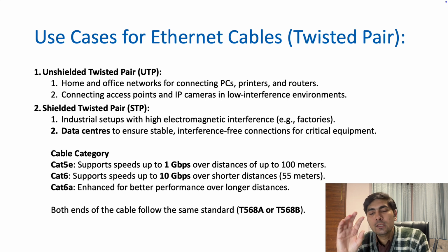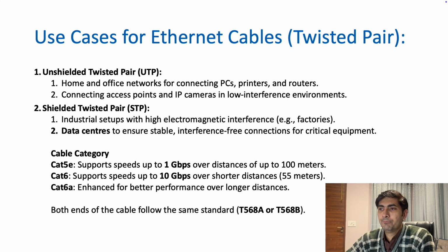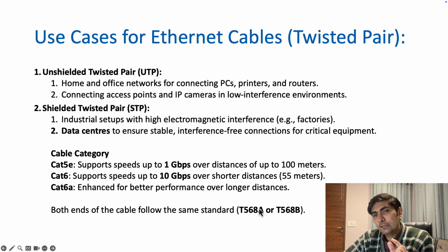All right, so I was saying that plus minus 2 volt is generally what each cable is capable of. And if there is a PoE device connected, then it can handle up to 40 volt each cable, just for your information. So these standards are as per that only. If you see, the connector will have 8 pins because we have 8 thin cables, so both ends will have 8 pins.